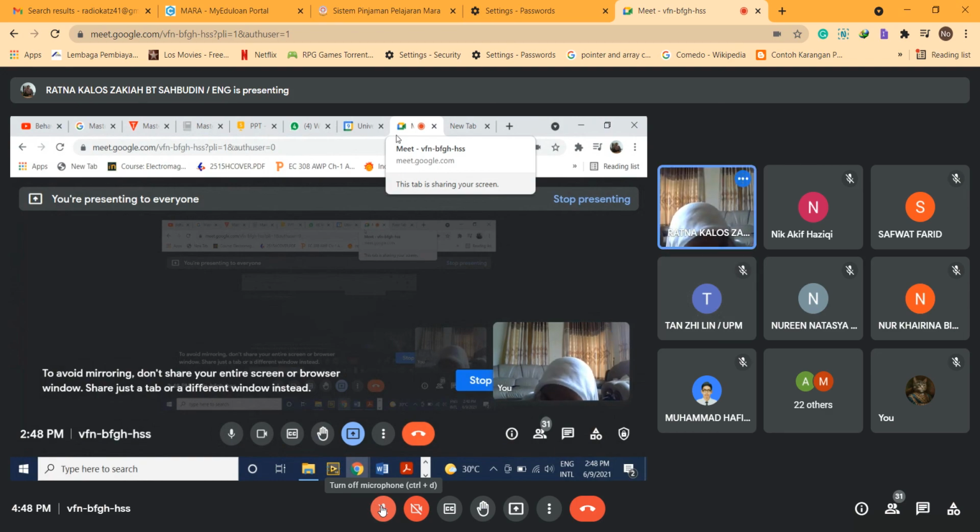Okay, so Doctor, before we end, can I ask about the master slave D flip-flop? Just now from the timing diagram, the lecturer has four outputs, right? The QM, QS, QP, and QN. For the master slave, yes, there is a glitch, so we use the master slave D flip-flop to avoid the glitch, so we get the output of QS, is it?